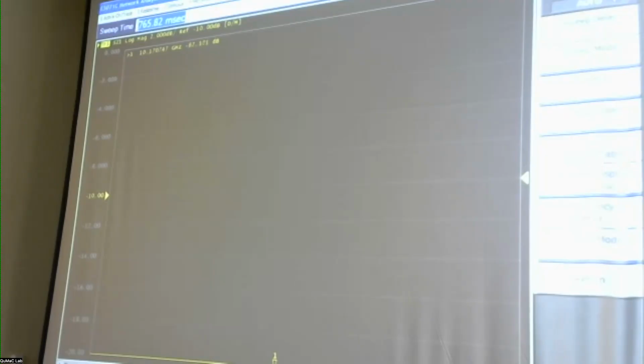So that's what you have to decide. This is exactly equivalent to saying that I'm averaging for longer at the same point to improve my signal to noise ratio. Now, in addition to the IF bandwidth, because that sets what is happening in one sweep, it's basically going to go to one frequency, wait for some time, integrate, calculate the value, then move on to the next step, and the next step, and so on and so forth.